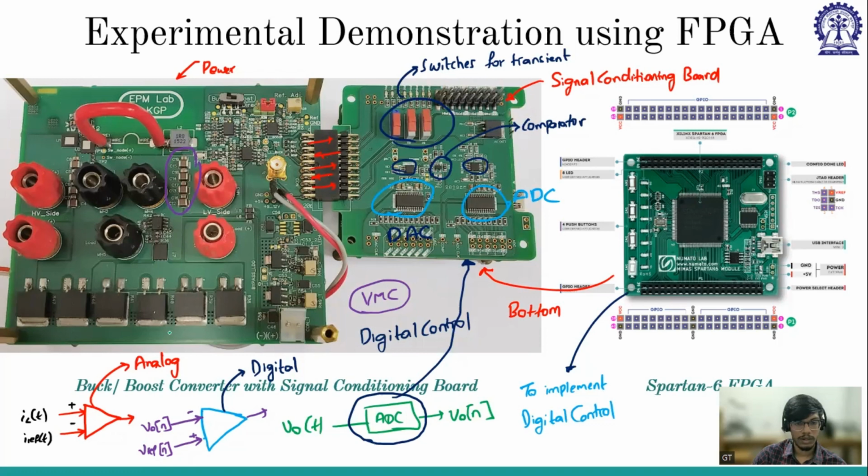Which means, sir, if I want a 40 microfarad capacitor at the output in our design, can I put four 10 microfarad capacitors in parallel? Yes, that is up to you. Like I have mentioned, there are two constraints. The first constraint is space: if you put many capacitors, it increases the space.